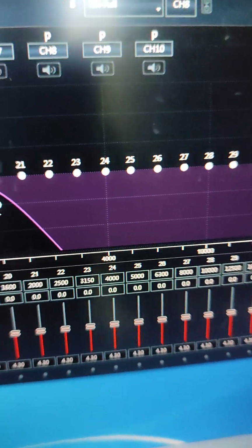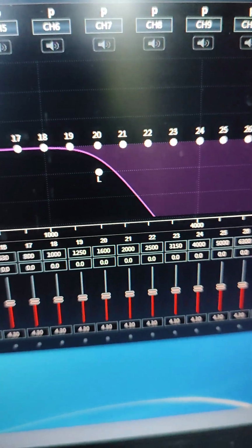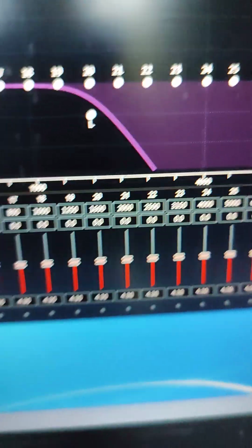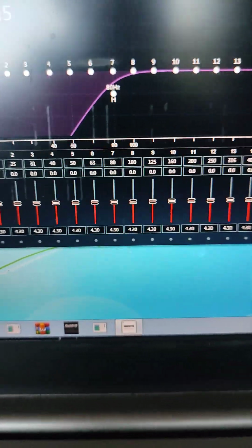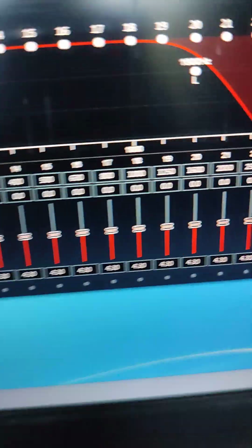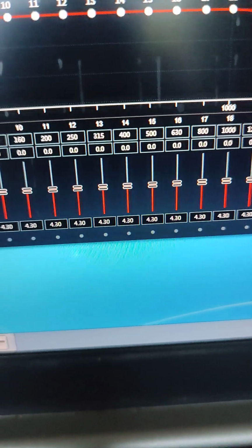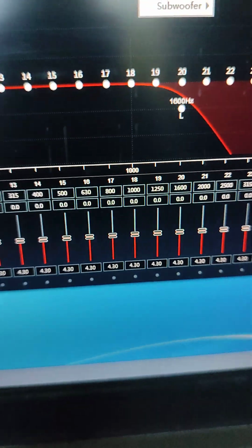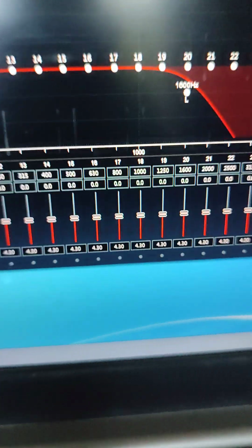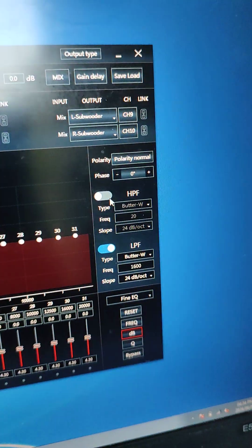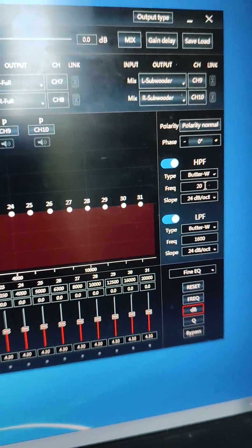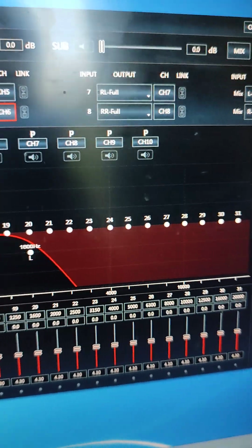Let's just give an 80 hertz there, say we're using a 6-inch, and this crossed over at 500, and then this frequency then will change to give front right mid-range woofer. Again, put on the high pass, make that an 80 to 500, representative of the speakers that we're using.